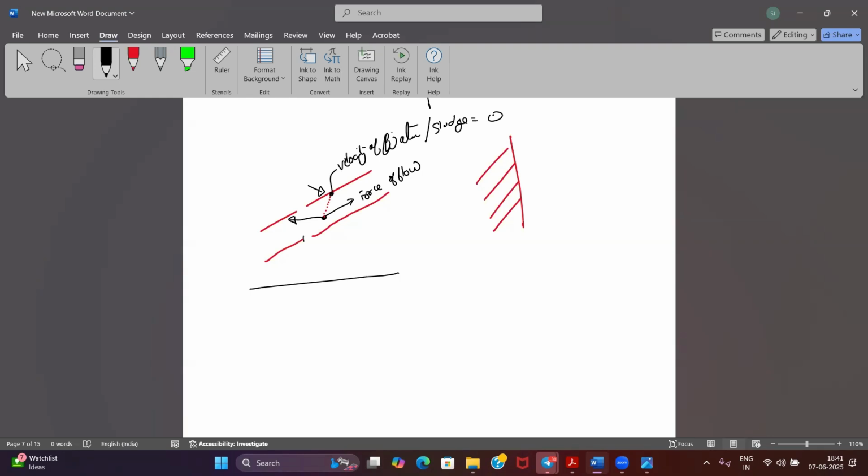It will be thrown towards this because of the resultant force. This is the resultant force in this part. It will be thrown onto the disc's top, and from there this will roll down and accumulate because of the centrifugal force. It will accumulate on the periphery now because the velocity is gone from it. It will be rolling down and coming down to the periphery of the plate. Is it clear?